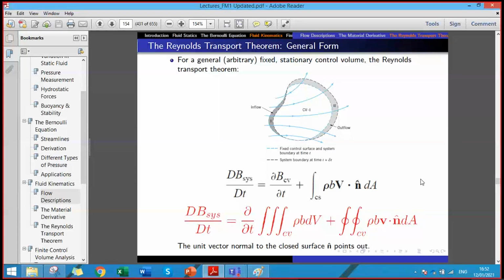But what happens if I place a sink inside the control volume? Let's say there is no inflow into the system and no outflow from the system, but still the temperature is changing. Then it means that there is some sink in the control volume, something absorbing temperature within it. Let's say I have placed a piece of ice inside the control volume, that would reduce the temperature, right? So that will include the unsteady effects. The first term expresses the unsteady effects, the source and the sink within the control volume. Or if I place a heater inside the control volume, the temperature will rise with time, even if there is no inflow or outflow of hot fluid. Clear? Yes, sir. Clear.